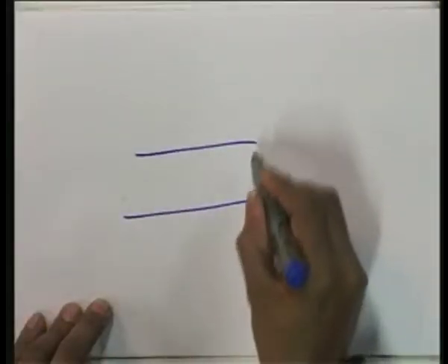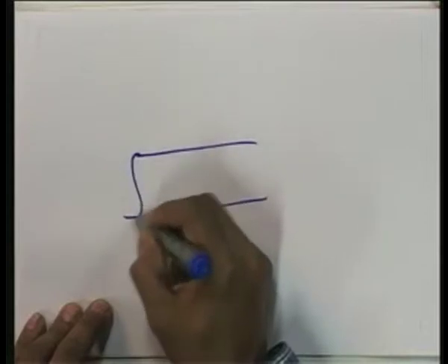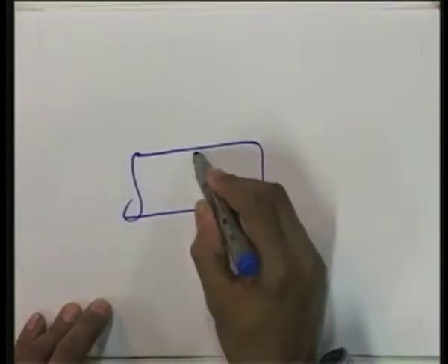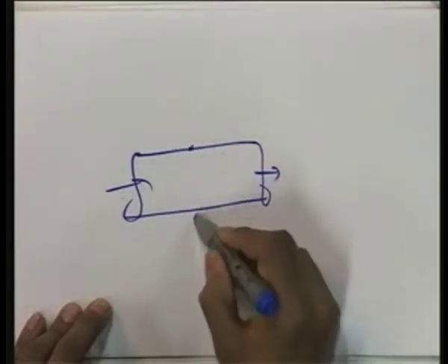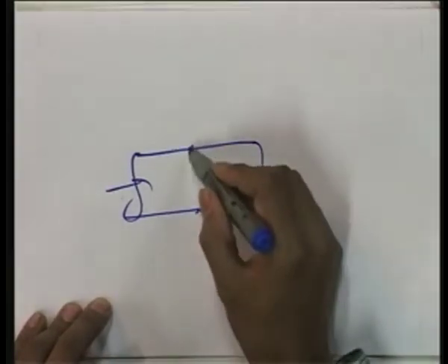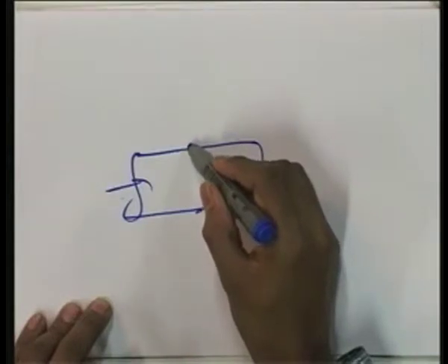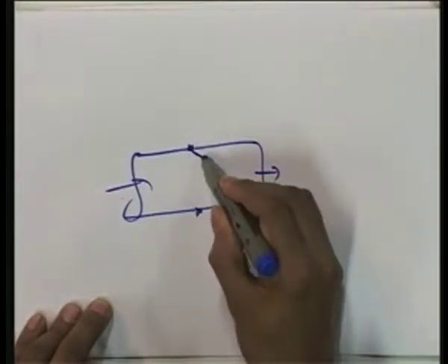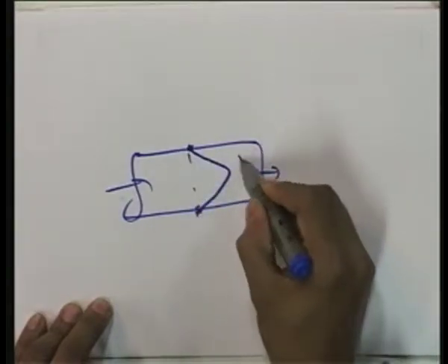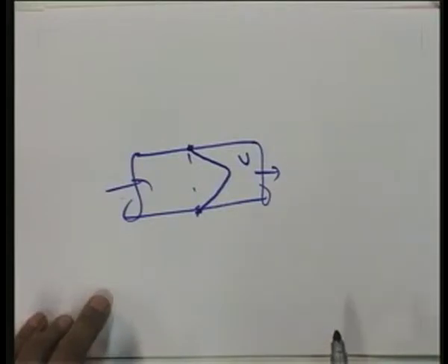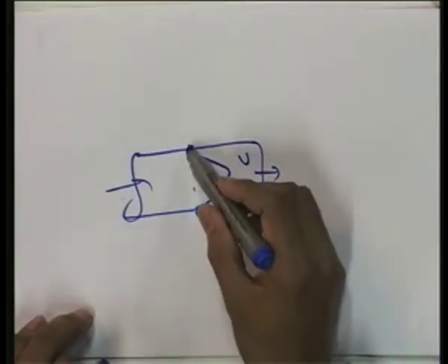So, you can see that if we consider the pipe flow, as far as pipe flow is concerned, say the fluid is coming like this, then the pipe is a solid surface, so the velocity should be 0 on this surface and this surface. So, you can see that the velocity variation is like this. So, this is the velocity, due to the no slip condition on the boundary.